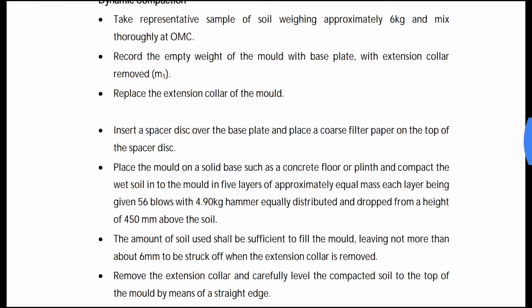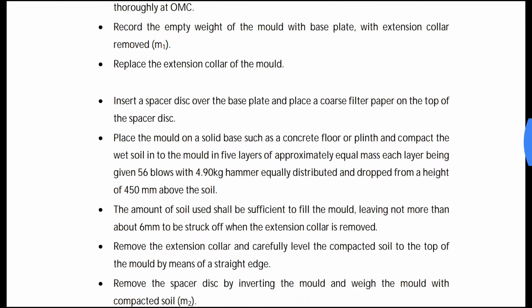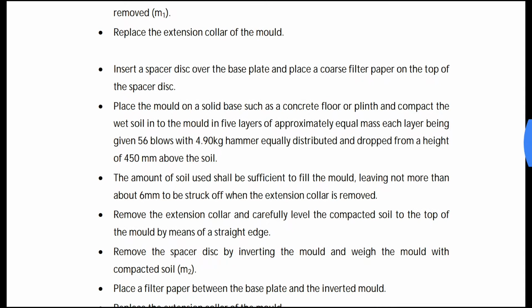Dynamic compaction. Take a representative sample of soil weighing approximately 6 kg and mix thoroughly at OMC. Record the empty weight of the mold with base plate with extension collar removed, M1.